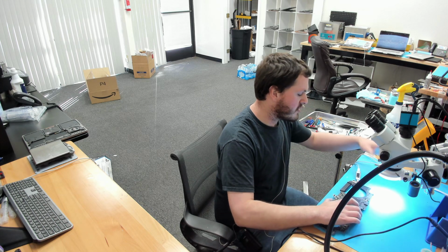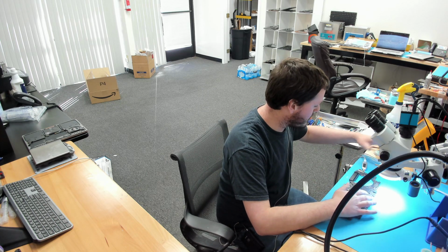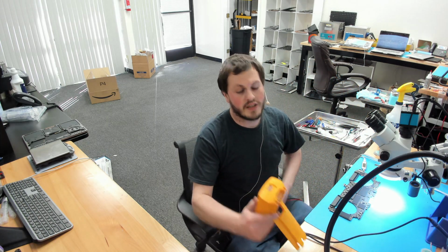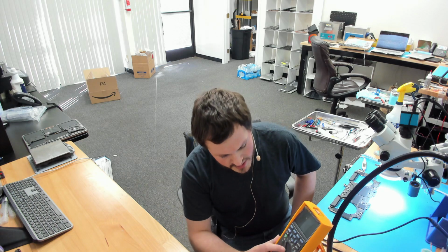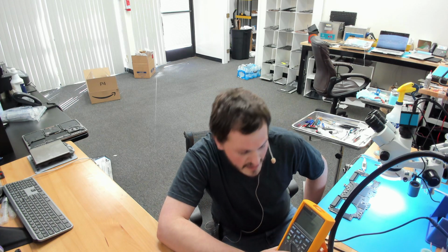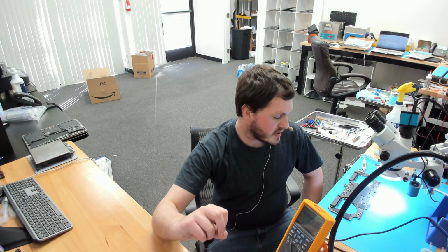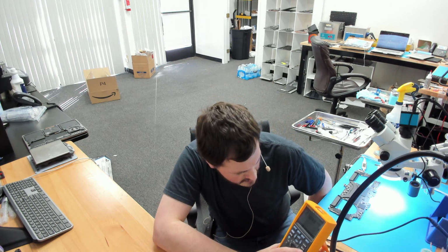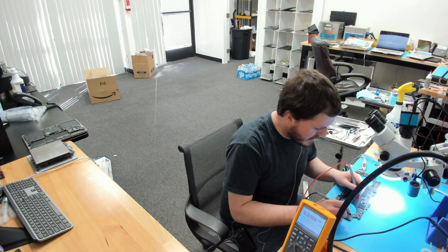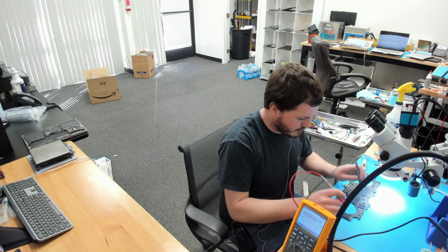The first thing I'm going to want to check on this board, because this is very, very common, is the SSD 2V5 NAND regulator. So I want to go ahead and check voltage on that. I want to see if it's outputting 2.5 volts to our NAND, because in order for this board to boot, it needs to load something called BridgeOS, which is basically the operating system for the T2 machine that's stored on our NANDs. So I want to check voltage and see if our NANDs are getting power here. I do suspect they will be, but I want to double check here.